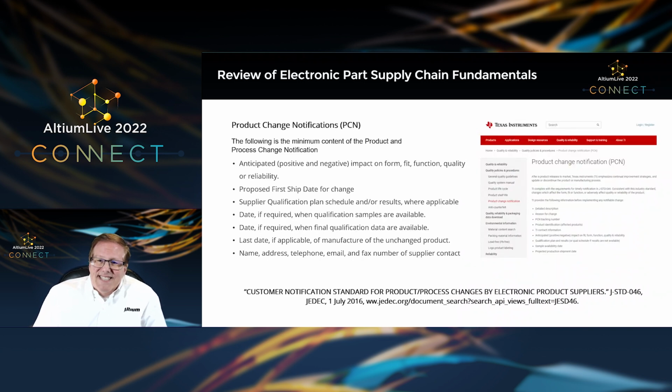It's essential to be aware of product changes, particularly those made to larger scale semiconductor devices. For example, situations have occurred where a seemingly innocuous die shrink of a DRAM device made by the manufacturer for margin enhancement resulted in intermittent field failures of released products. This was due to subtle timing differences between the pre and post die shrink devices and the fact that the product design operated near the edge of the timing window.